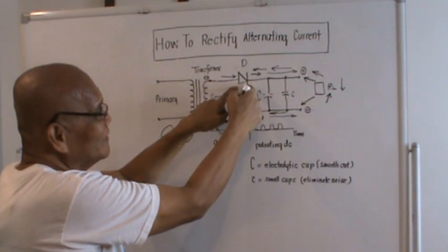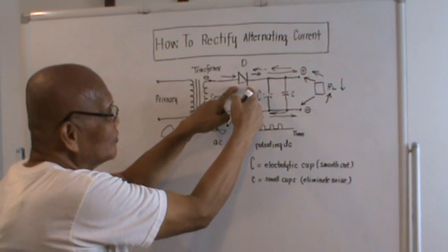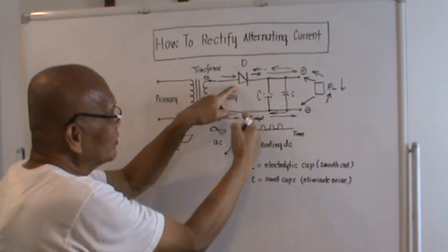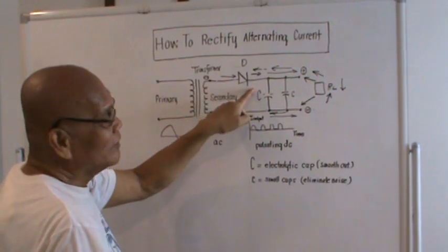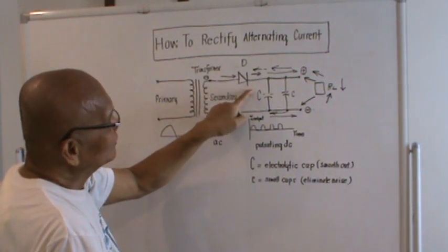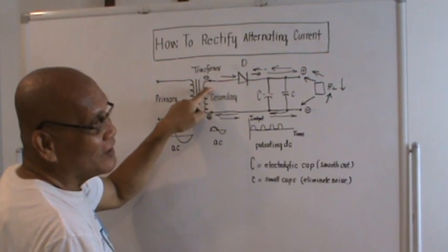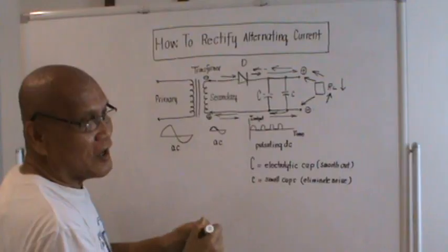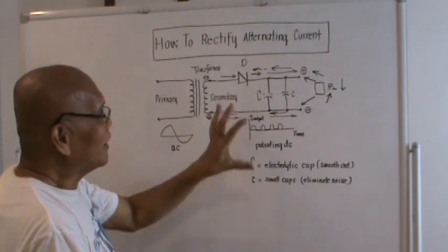to the cathode. Since this current here is against this diode here, this current during the negative alternation could not pass through the diode. If it could not pass through the diode, it could not go back here, right? So it seems the circuit is actually off during the negative alternation for a half-wave rectifier.